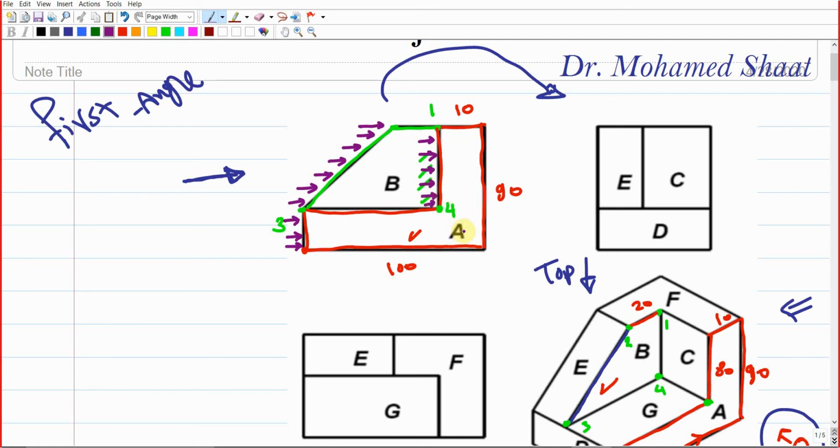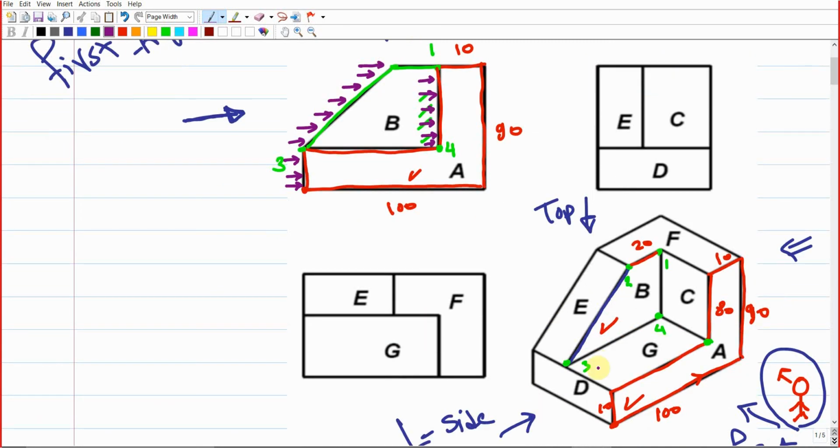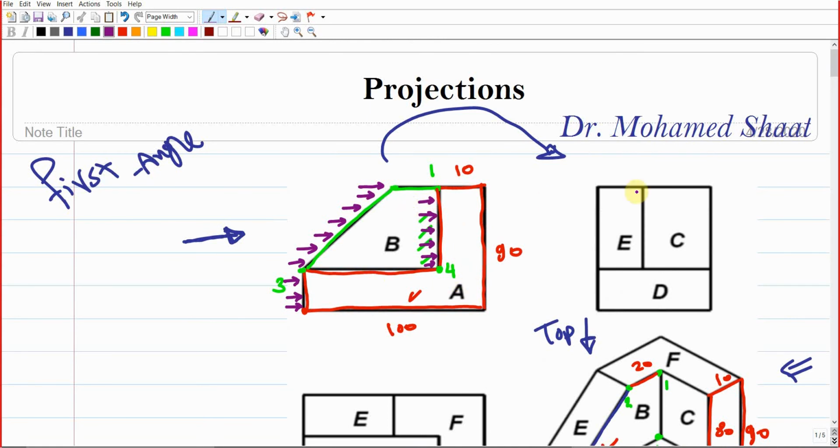What I mean here is that I didn't even go to the side view yet. I just finished the front view, and now I'm preparing to draw the side view. To prepare, try to imagine that you're gonna look at it from this angle. Why this angle, not the other one? Because this is the left side and it should be represented on the right of the front view. Make sense?